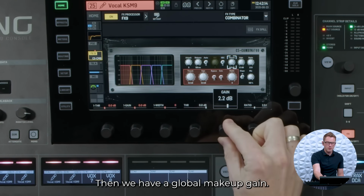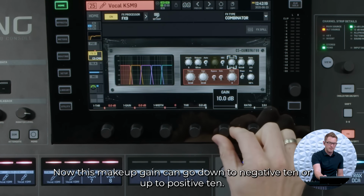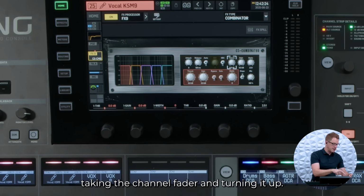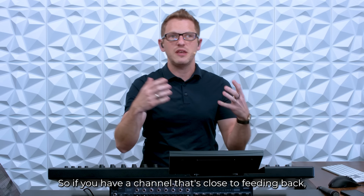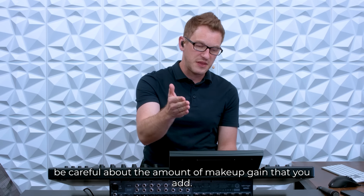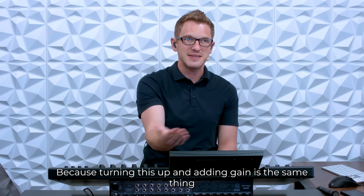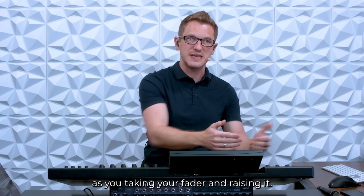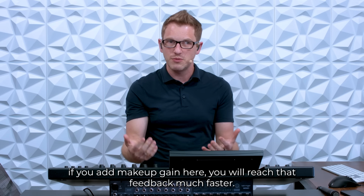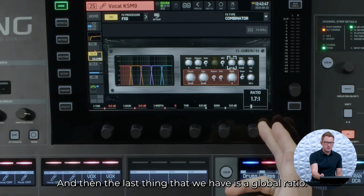Then we have a global makeup gain. Now, this makeup gain can go down to -10 or up to +10. And again, this gain knob is just like you taking the channel fader and turning it up. So if you have a channel that's close to feeding back, be careful about the amount of makeup gain that you add, because turning this up and adding gain is the same thing as you taking your fader and raising it. So if you're already on the verge of feedback, if you add makeup gain here, you will reach that feedback much faster. And then the last thing that we have is a global ratio.